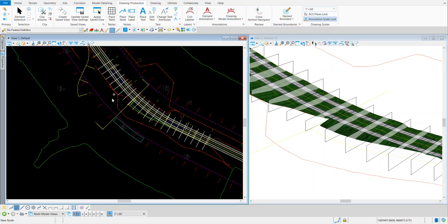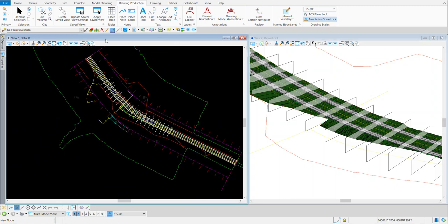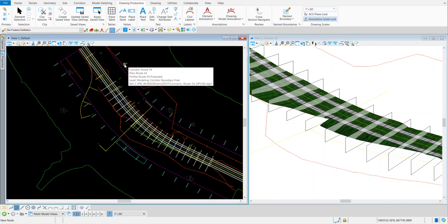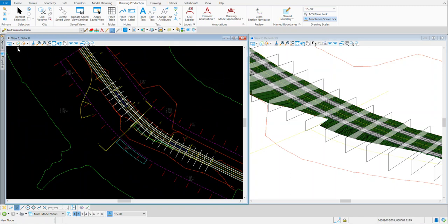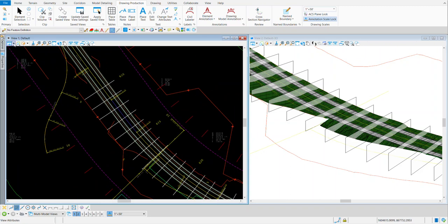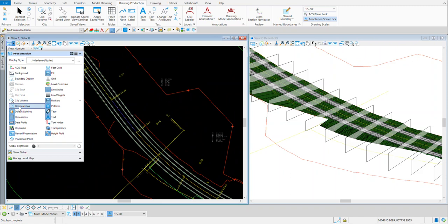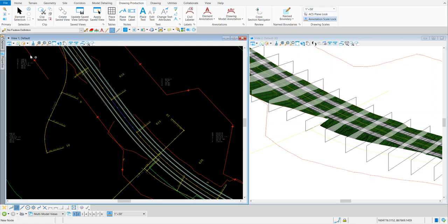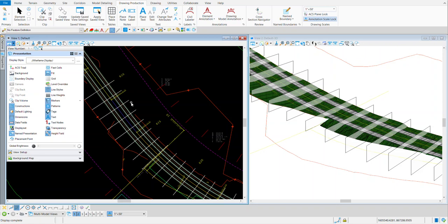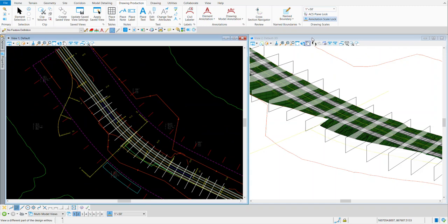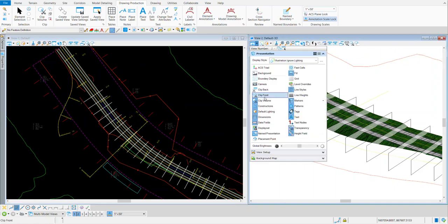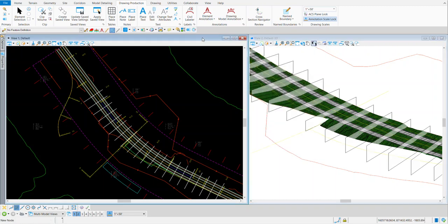On the left side, I'm going to go back over here and make my View 1 active. You'll see that we've got our handles and our template drops, and we've got all kinds of information here. If you didn't see the pattern lines as you placed them out, you want to verify that constructions is on. If the constructions are off, you don't see any pattern lines. And that's a big tip. Sometimes people create them and they don't have their constructions on in that file. For some reason they're off. But if you turn them back on, you're good to go. So constructions. That's how you see the name boundaries.